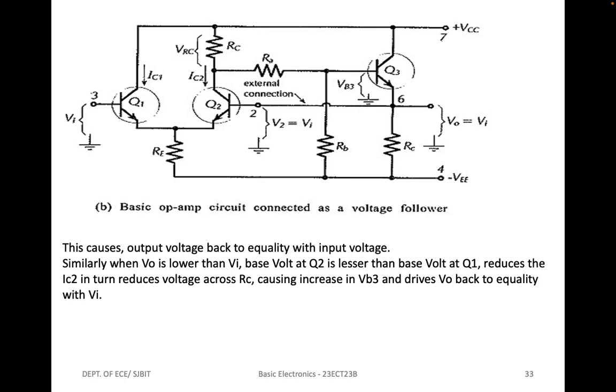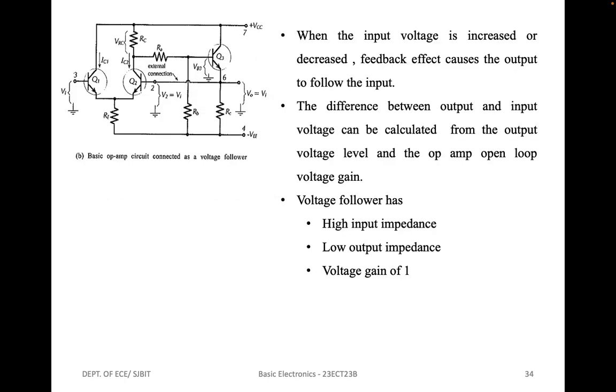The voltage follower also has a much higher input impedance and a much lower output impedance than the emitter follower. Actual values of Zin and Zout can be calculated from the negative feedback equations, which are derived by assuming certain parameters.